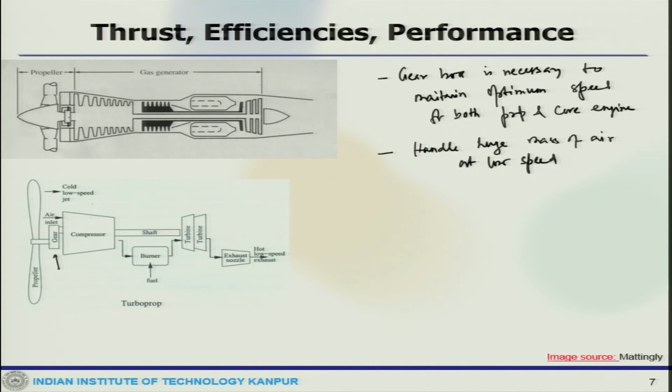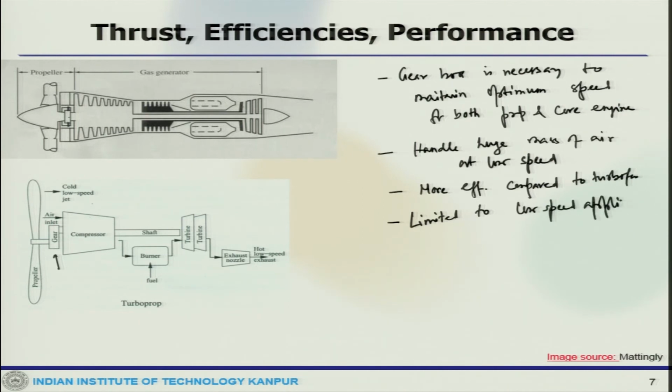So, in low speed applications, this is more efficient compared to a turbofan, but as I said, this is limited to low speed application, because when you go to high speed, there is the possibility of propeller tip shock waves.